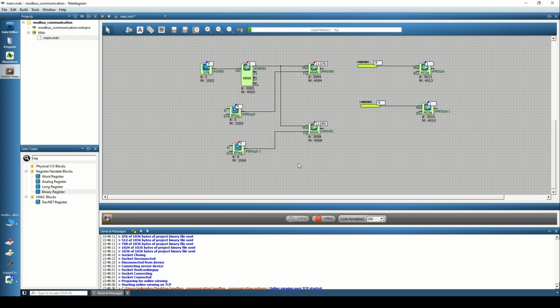The connection is still there now. So, there is no change in the MODBUS status. I'm disconnecting the connection now. I sent another trigger, and this time the status was lowered to 0. So, if there is a connection problem with a device via a 485 line, I received a 0 response in the query I sent. In a situation where one energy analyzer may have a connection problem or may have lost power, you can get the communication connection information from here.